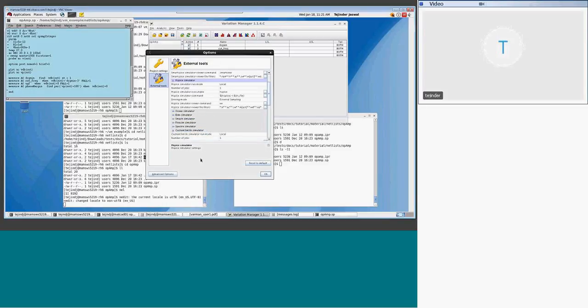The setup is minimal, and once you have those netlists, like the band gap, it's good to go. If there is any error or warning, you can check the file in your home directory, in the .silvaco directory. Under there is the variation manager, and there's a log file. You can parse those and see the error. If it's not running, you can see the detailed error and fix it.